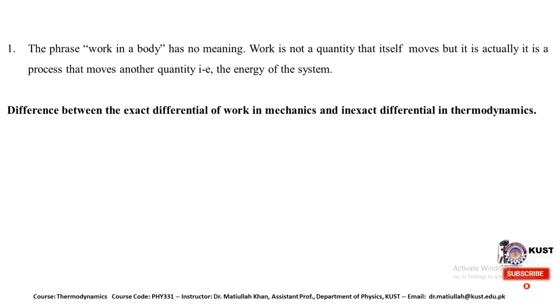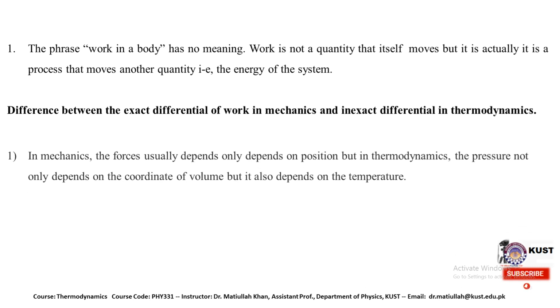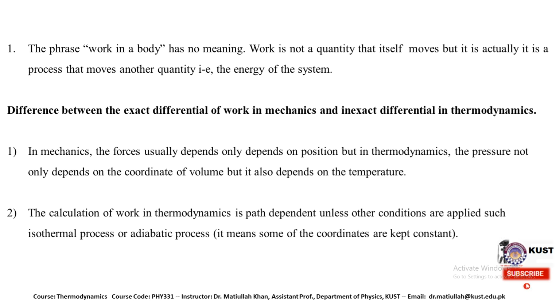So if we compare the exact differential of work in mechanics and the inexact differential in thermodynamics, we have some basic points. In mechanics, the forces usually depend only on position, but in thermodynamics, the pressure not only depends on the coordinate of volume, but it also depends on temperature.